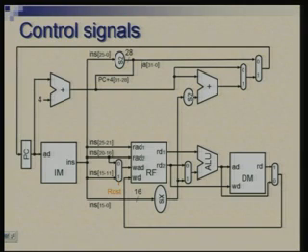So, all multiplexers would require control, and in this exercise of identifying control, we will assign names for the purpose of reference for all the control signals. We will call the control signal for this multiplexer RDST, or register file destination. It will select the destination address in the register file, whether it comes from here or from here.